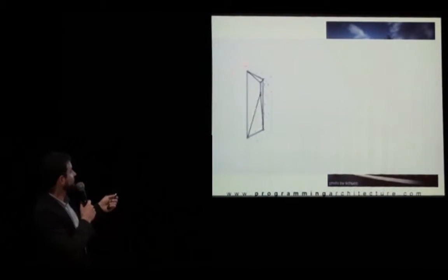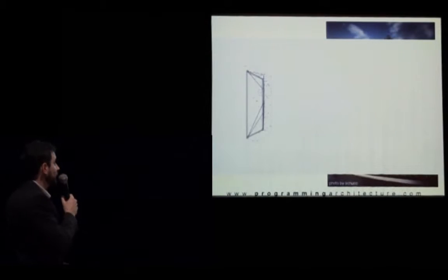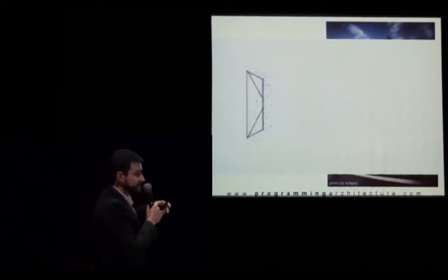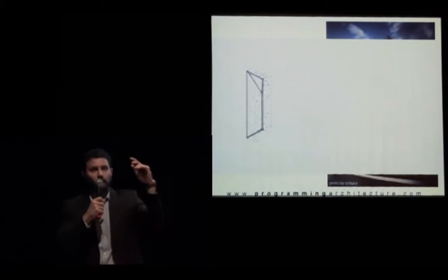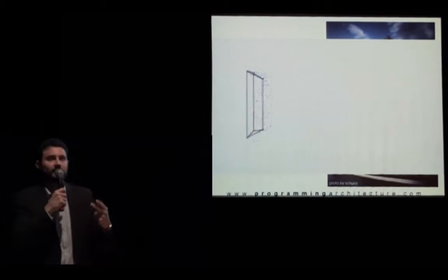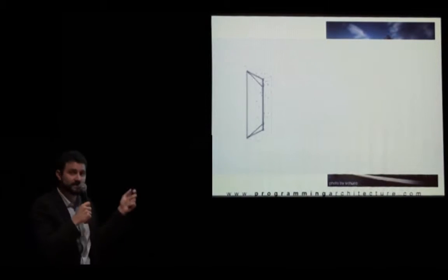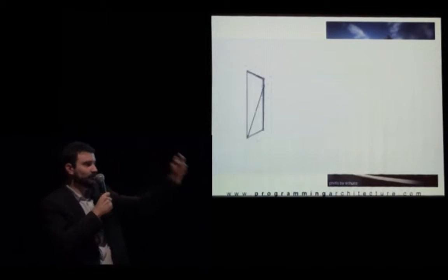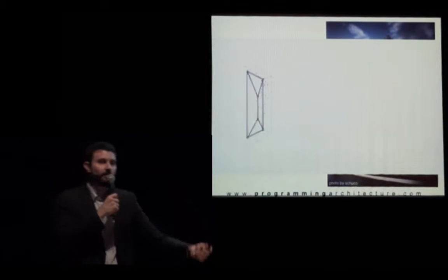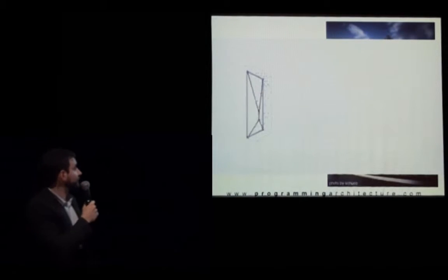You can't see here, but it's a pretty complex model. It has like 2,000 structural members. And it tests lots of geometries and basically creates a point cloud of the solutions that are not statically acceptable for that specific aluminum profile. So the architect, if he chooses that profile and that frame, has exactly, graphically shown, the red area and the green area, where he can design his facade element and where he cannot.